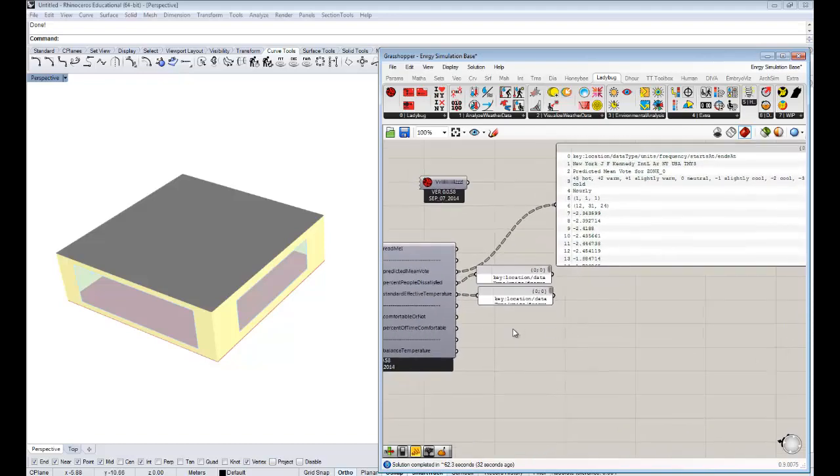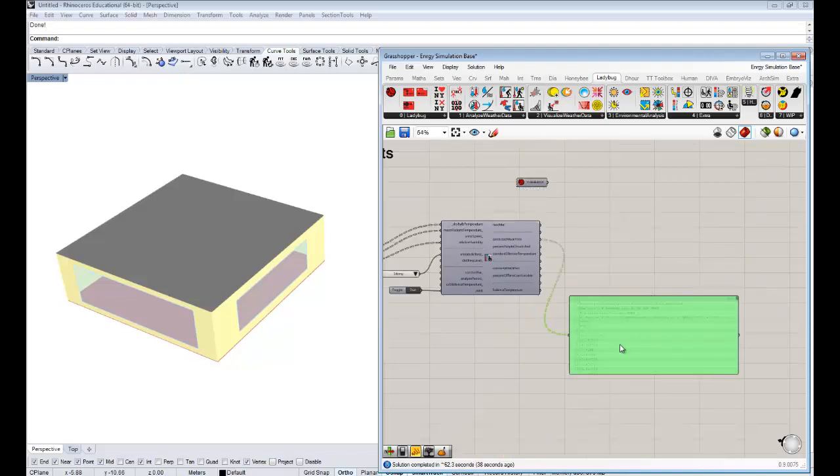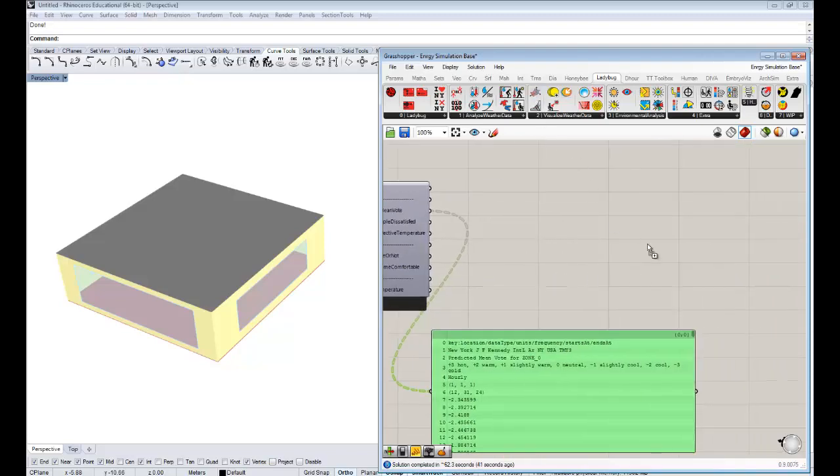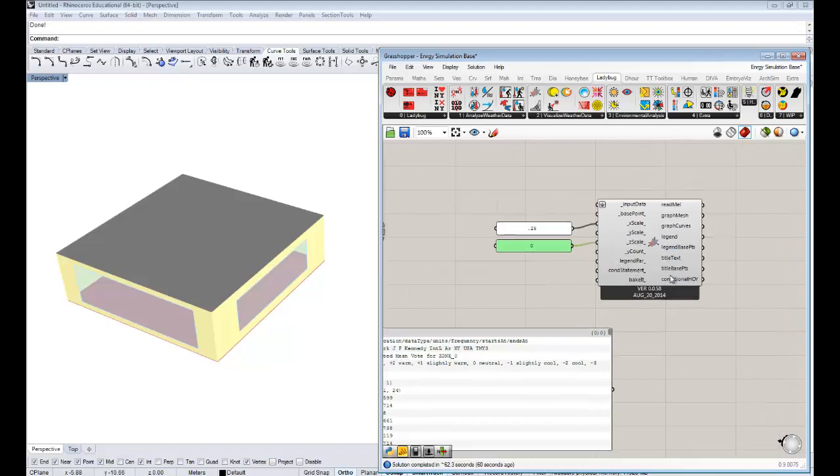And so now we can do stuff like, I'm going to delete this again because we're probably mostly interested in predicted mean vote here. But we can plot this now on, say, our 3D chart that you may remember from our last video. And I'm just going to set up the situation that I like here, where we scale the x by 0.25 and the z I like to set to 0. I'm doing all this beforehand because it can take a long time to plot all 5 different zones.